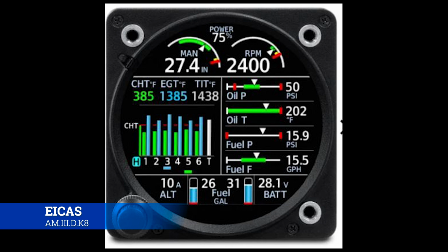Now the section to the bottom left is all about engine health, right? So CHT, EGT, TITs, that's turbine inlet temperature, is all happening right there. Then you have the different CHTs and EGTs per cylinder. If you had one that was way off or way out there, then you would know there was something wrong.